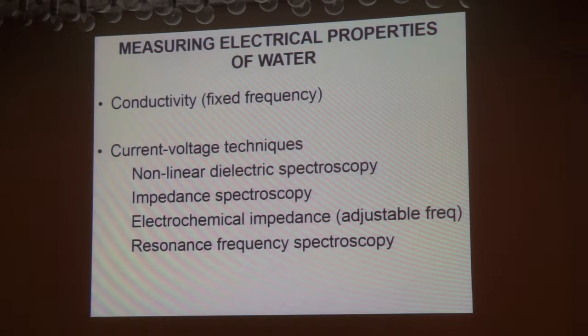Now, this concept is used in nonlinear dielectric spectroscopy and impedance spectroscopy and electrochemical impedance. I've done some experiments with this method because it allows you to adjust the frequency. So in experiments we'll talk about later with electrochemical impedance, I adjust the measurement frequency to be the same as the excitation frequency.